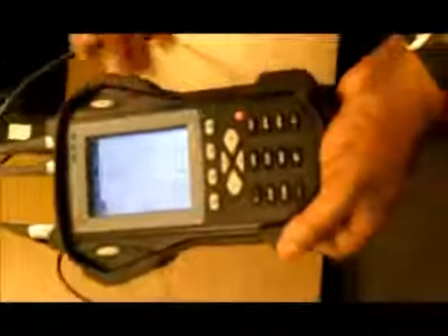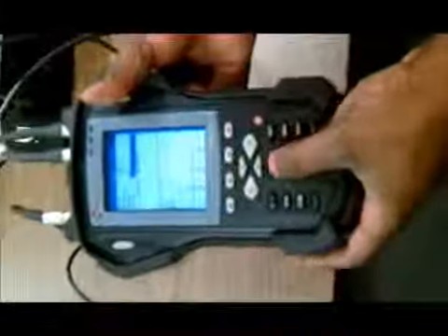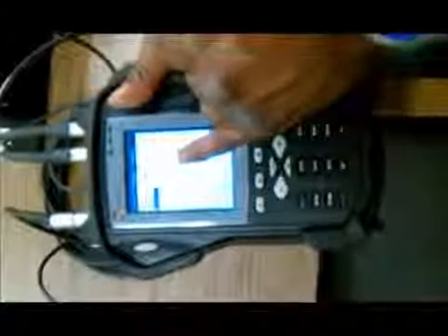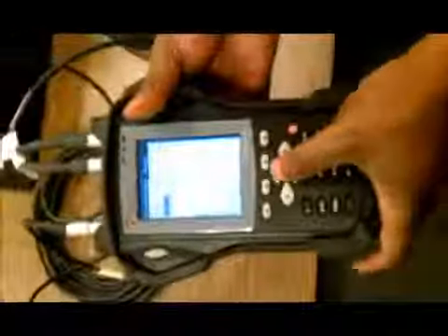In this instance, we need to add 0.278 grams at an angle of 144 degrees, and a radius of 1 inch. The good thing about the 258 is if we decide that 1 inch isn't where we want to add it, we can change the radius, we'll say 2 inches in this case. And what it does is it compensates. As you can see, it dropped our mass by half because we've doubled our radius. And vice versa, if we make our radius smaller, it's going to take more mass to do that.